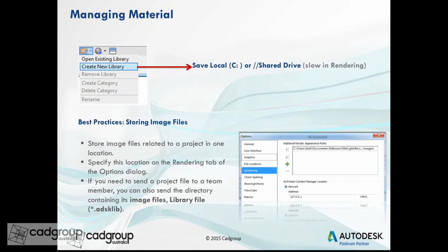If they transfer the project from one PC to another, when they render, some of the rendering doesn't come out with the proper material they have assigned, which is obvious, as the custom images or materials that you apply are reference files and not saved with the project.